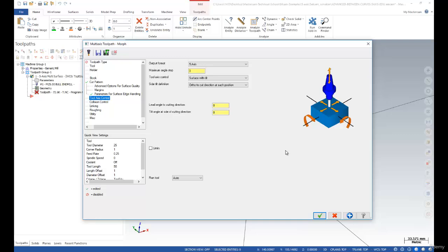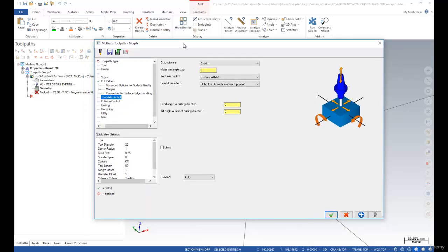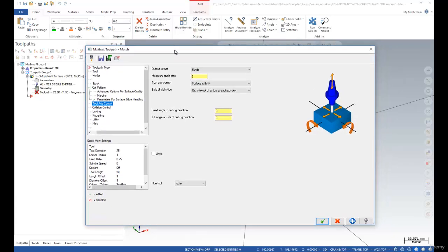So that's why tool axis control is quite important. When I am controlling my tool axis, it means that the other options about the 4 axis, I'm going to delete all of them. So only one option. After that, it's okay. Mastercam exactly knows what I want. So this is the main idea. So that's why I need to control, and I need to give some parameters about the tool axis control. So I can click on the format. This is the main idea.